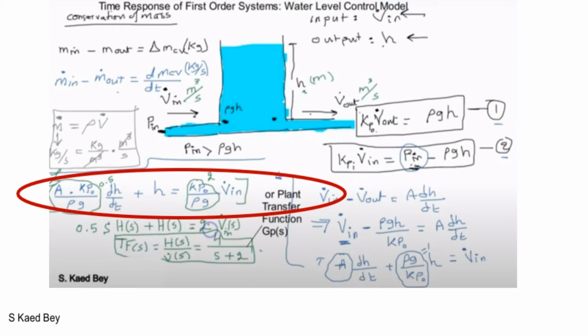From the tank model shown, the system output is normally arranged on the left-hand side of the equation, and the system input, which is normally shown on the right-hand side, is the volumetric flow rate. The convolution will allow us to find the corresponding output for any desired input if we have the impulse response of the system.